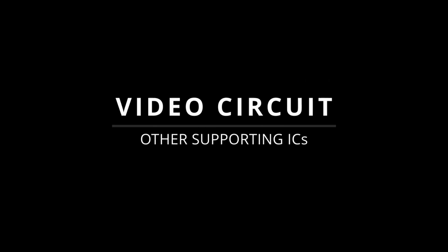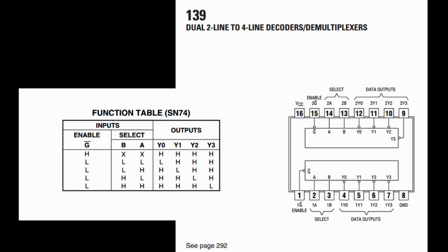The other supporting ICs, one to note, is the 74LS139. This is a 4-line decoder demultiplexer. It's a fancy name, and in this instance it's just taking 2 bits of data and deciding which of the 4 outputs to select. As you can imagine, with 2 bits of data we can create 4 possible combinations of 1s and 0s.